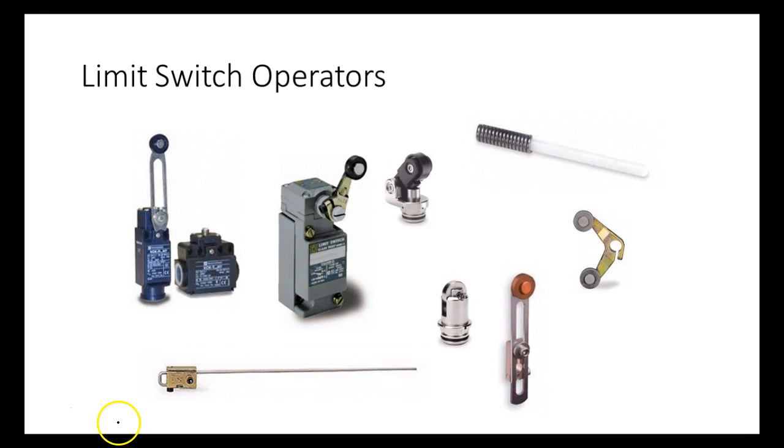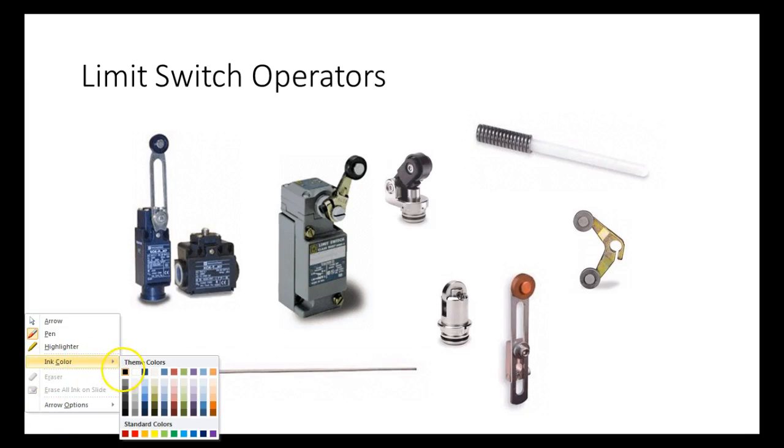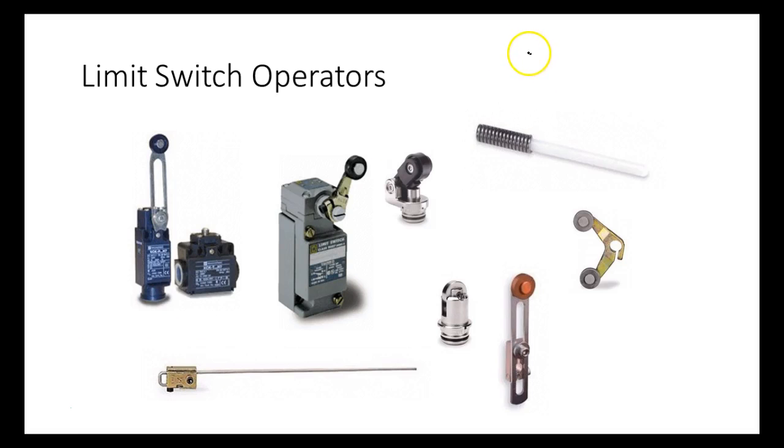We have several symbols, by the way, and this is also true on the schematics for the PLCs. Now what we do, guys, is we look and see what gravity is doing. Gravity's trying to open this, so this would be what we call a normally open limit switch. If I drew it like that, that would be wrong, right? We would call this a normally open being held closed, because gravity's trying to open it, right? So it must be something.